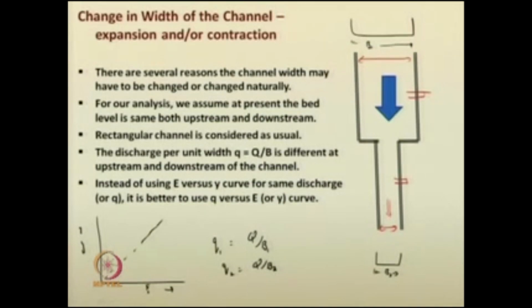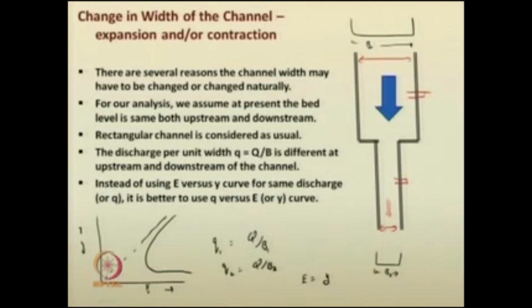In the earlier case which we have discussed, the width of the channel is not getting changed. So, you have E is equal to y plus small q squared by 2g y squared. For a rectangular channel, you have E in the following form.